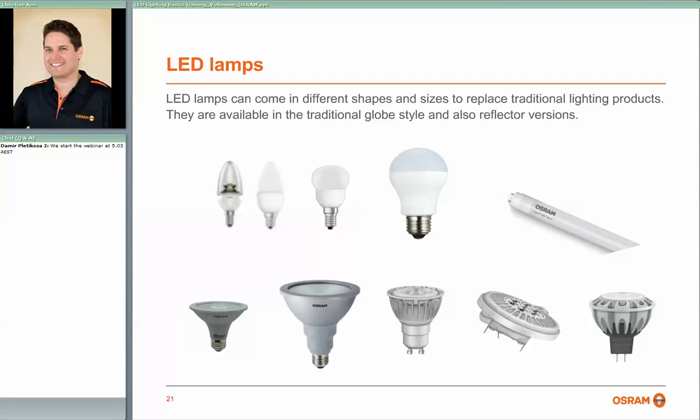So if you've got a completely confined fitting where the lamp doesn't have any ventilation or additional support from the fixture itself to draw away some heat, then potentially it can adversely affect the lifetime of the product. It depends on how hot the actual product will get. With the higher wattage products, there'd probably be more of an issue, because they would tend to get hotter, of course. So that's an important thing to check.